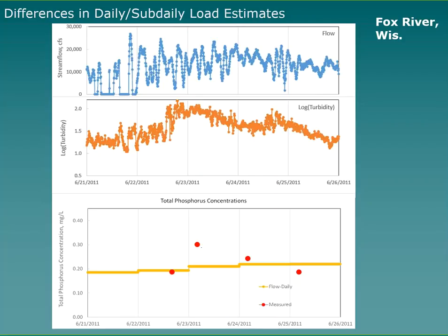time period. We started off with our daily flow model. What we're seeing is that as the flow goes up a little bit and as we go with the season, the concentration on each day is consistent since it's a daily model. You can see it doesn't do a bad job. It sort of hits the average of the concentrations, but doesn't really predict the daily variability. When we go to the UV flow model, again, we're seeing very little relationship with flow. As we go through these wide ranges in flow, we're only seeing a small change in the concentrations, which says that the flow is really not related to what's happening here. But again, it sort of hits the middle of the concentrations.